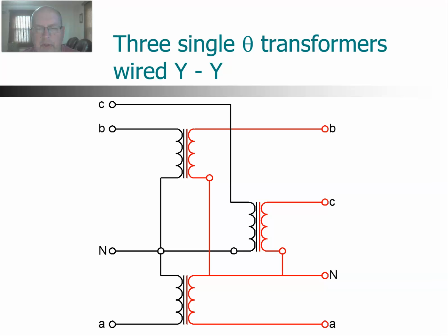Another thing to be aware of is how do transformers work in a three-phase circuit? Well, it turns out it's actually pretty straightforward. Essentially, all we do is use three one-phase transformers, but like the sources and the loads, we can hook up the primary and secondary of the transformers in either a star or a delta. And remember, star and Y are the same thing.